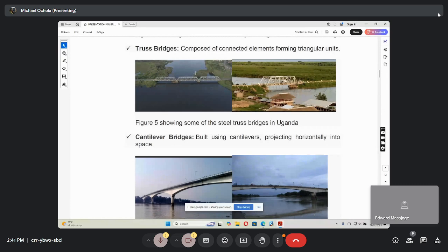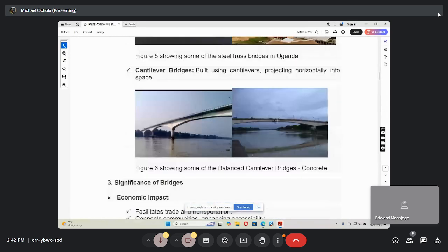But now, where we are going and where we have reached with population outburst and interconnectivity countrywide, there are areas that demand long span bridges. Even for you who design buildings, we are not going to be having columns at only 6 meters. You are going to have free span of 20 meters in design. So both columns and slabs will also be pre-stressed. And in the pre-stress, you have what they call post-tensioning and pre-tensioning. That one we'll learn later.